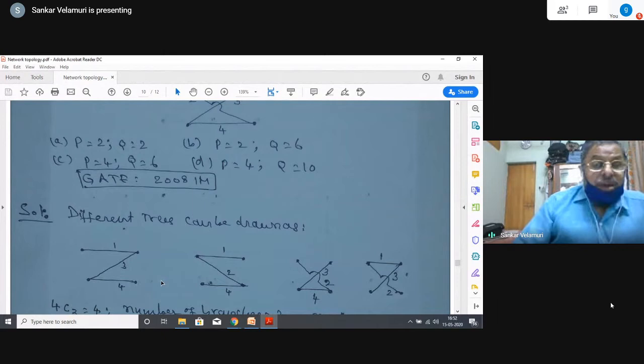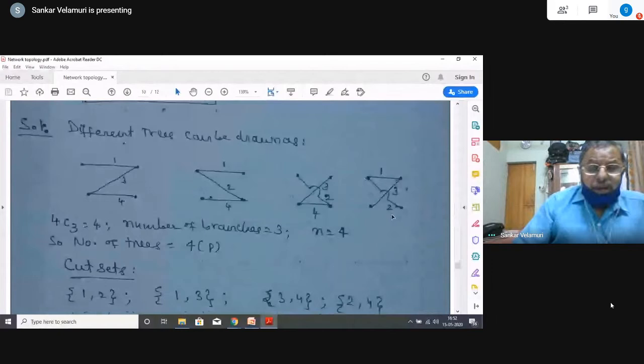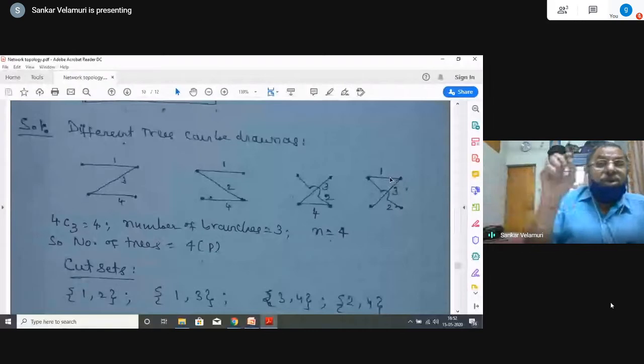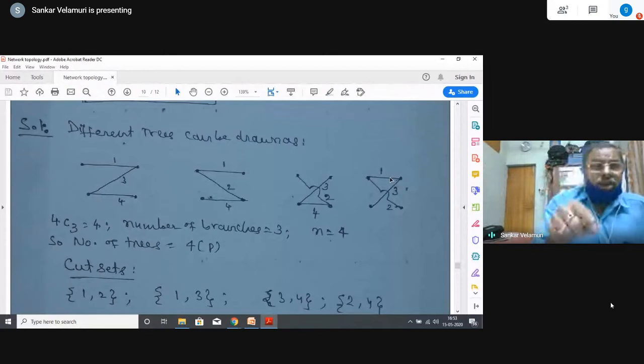These 2 nodes are isolated, these 3 nodes are isolated. So this is another cut set. That means it is a combination, and more than one node is being cut. Therefore it is not related to only one vertex. I have related that to one vertex only. With respect to one vertex, if 2 elements are sufficient, why give 3 elements? That is not necessary because it becomes a superset.